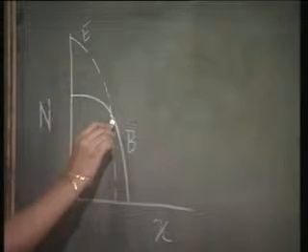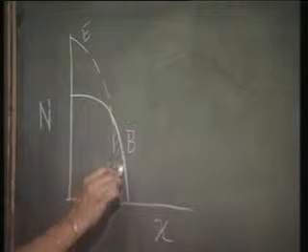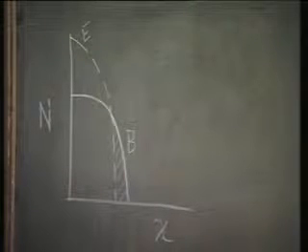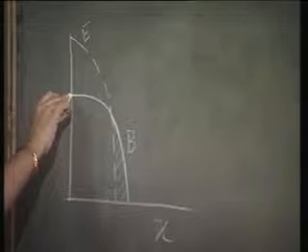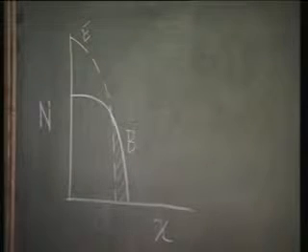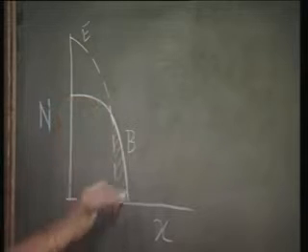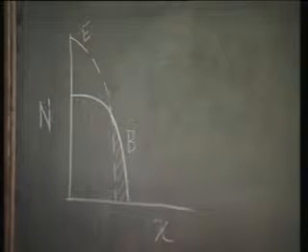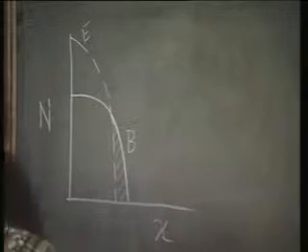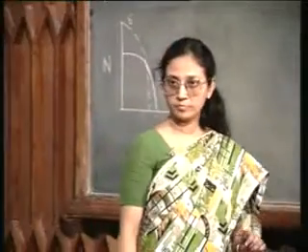I have only a small total charge in the active base region. However, as far as the extrinsic base is concerned, I see a much higher total charge with higher surface concentration. That is, the region surrounding the emitter has the full benefit of this implantation profile, and it has a much higher doping concentration and therefore much lower resistivity. Clear?